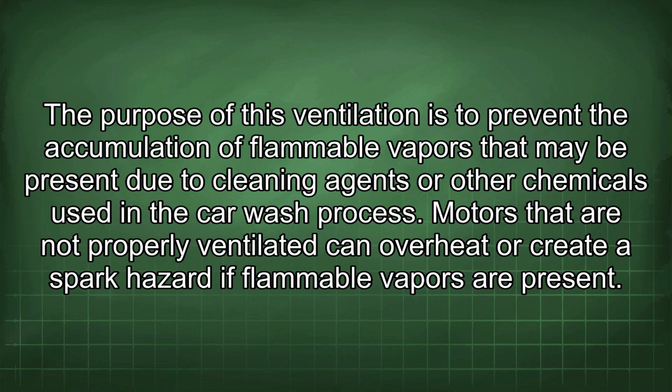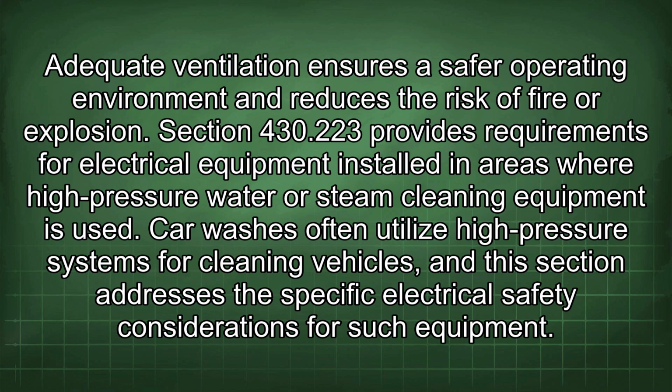Motors that are not properly ventilated can overheat or create a spark hazard if flammable vapors are present. Adequate ventilation ensures a safer operating environment and reduces the risk of fire or explosion.